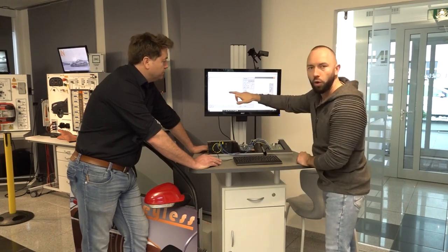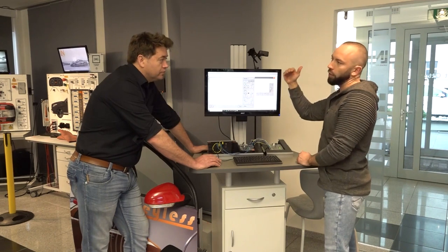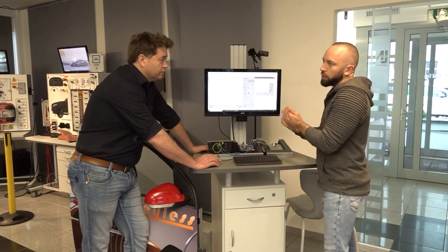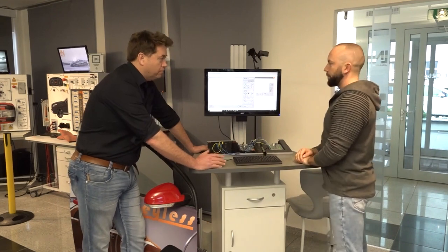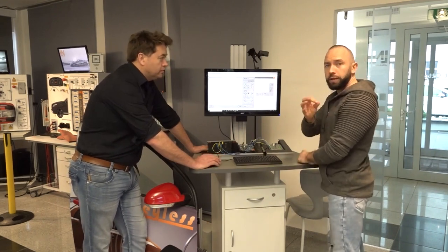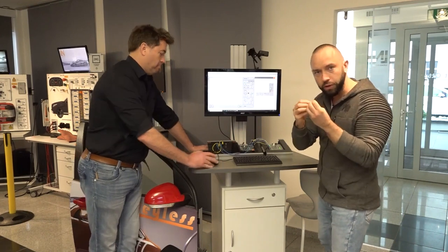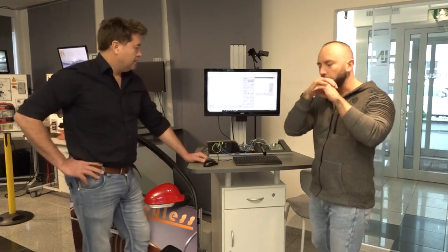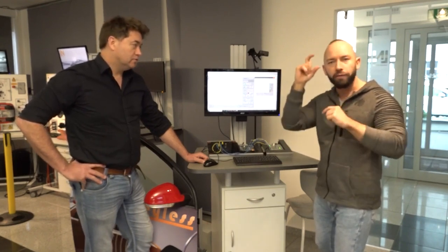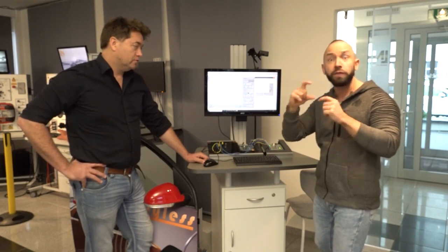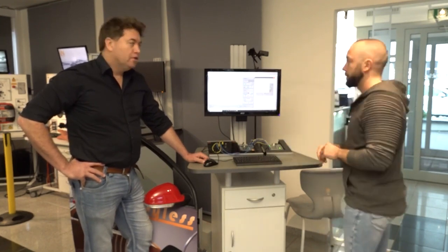When I see that CAN low, for example, is always at 5 volt, then we obviously have a problem. So you can use the multimeter for a first diagnosis, if you just want the fundamental diagnostic and easy information on whether the average voltages are fine or whether you already see a problem.